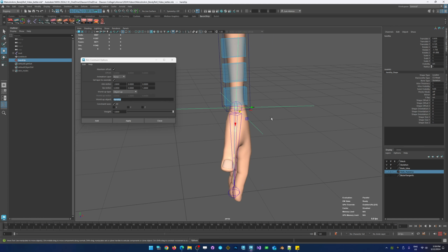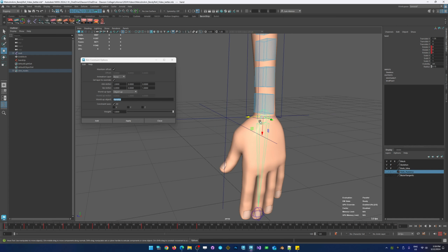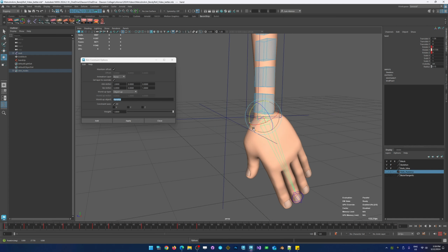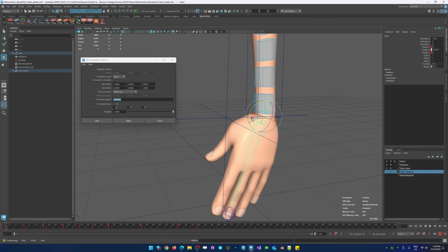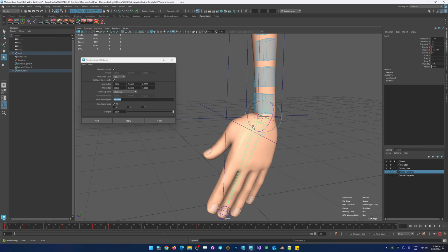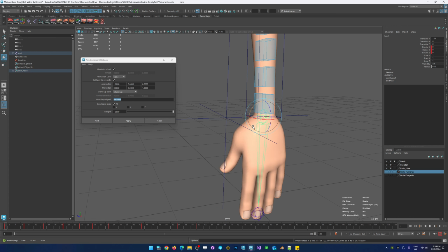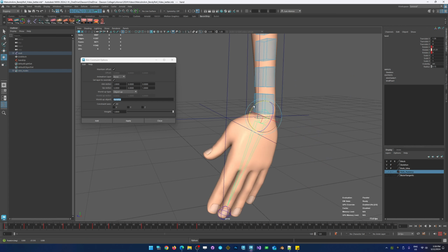So the solution to this, and this is why most people set it up this way, is that they grab this thing, and instead of using the up vector on the z, they will use this other axis where your rotation here, in this direction, most human beings cannot really bend their wrist in this direction very easily. We all can only do about 15 to 20 degrees. And if you're one of those people that says, oh no, I can do a lot more than that, that's because you're probably twisting your arm and you're actually doing more of this than you are of this.